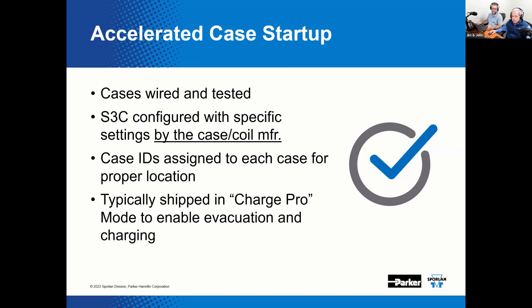Now, another thing, in order to facilitate pulling a vacuum on the system, this is on the actual plumbing side of things. Prior to charging it with refrigerant, it's really handy to have all valves that are physically in the system in an open position. So that would mean all Sporlan EEVs, EPRs, and solenoid valves would be open. Now we ship the electronically controlled valves from our factory at a 50% open position. That helps somewhat.